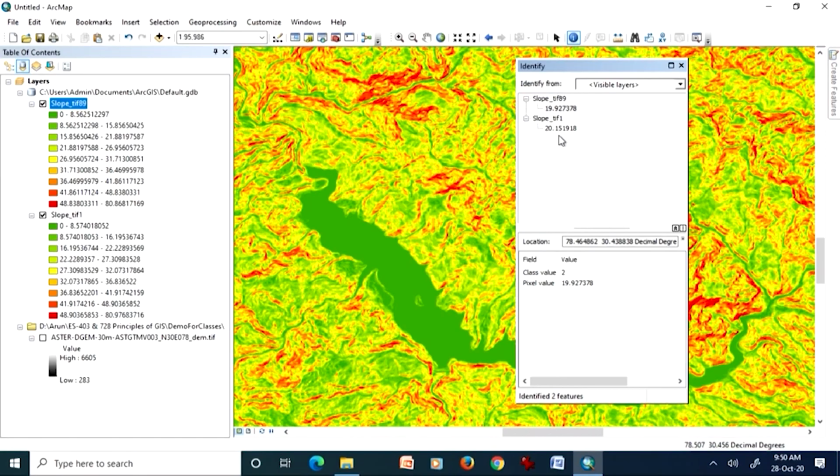So again here, when we keep jet factor 1, which is not correct in this case, because latitude and longitude are in decimal degrees, whereas the third axis, that is the z axis or vertical resolution, here is in meters.